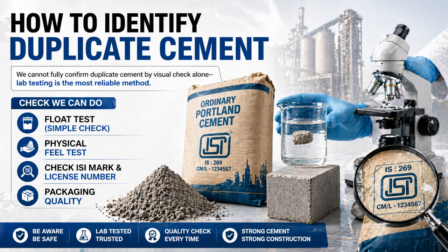The first test is the float test. We have to take a pinch of cement, and it should float on water for a few seconds before sinking. Sinking immediately may indicate adulteration. Physically, the cement should feel smooth, not gritty, free from lumps, and the bag should feel cool inside.